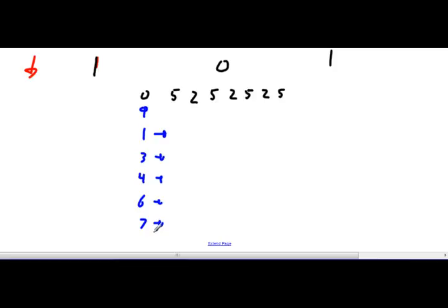I see where the J value came from for the first flip-flop, which is connected to the 5 volts. On the second, I can see where the 0 for the J comes from, but where did the 1 for the K come from? Well, if the initial value of the first flip-flop is a 0, 1 for the Q and Q naught, then the J would be 0 and the K would be 1 for the second flip-flop.